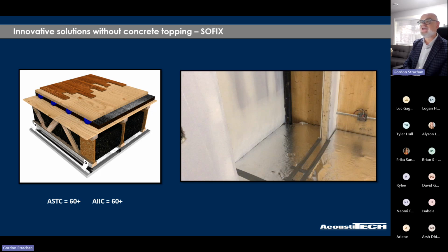But the one thing you may notice on this drawing, they're running conduit underneath it. So up to 1.5 inches of conduit, you can run between those blue balls in the diagram on the left that are the supporting rubber balls for the material that treats the void space between that and the subfloor.